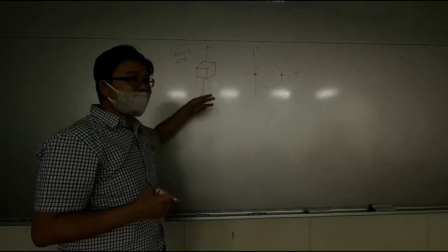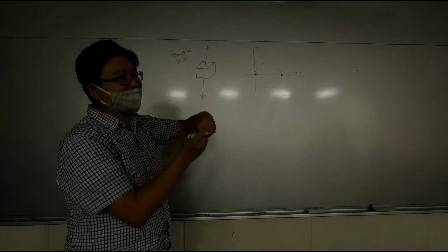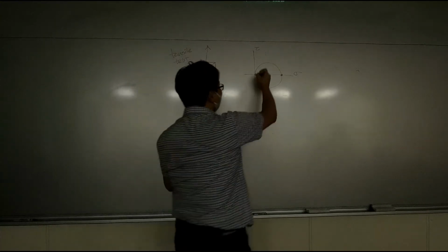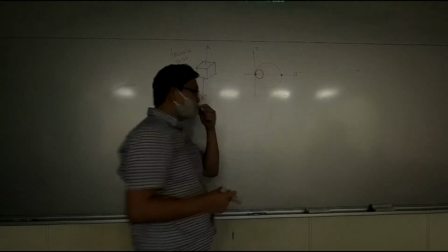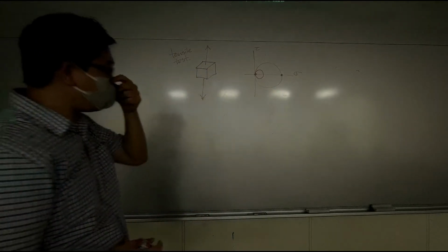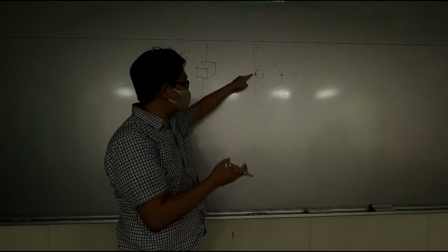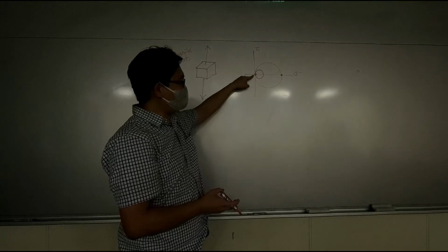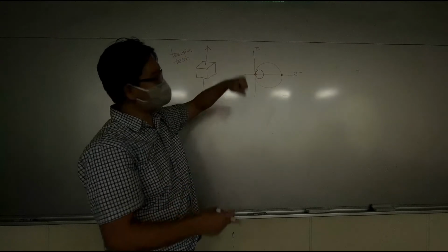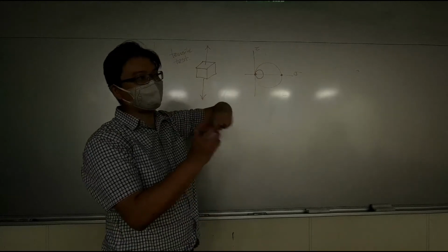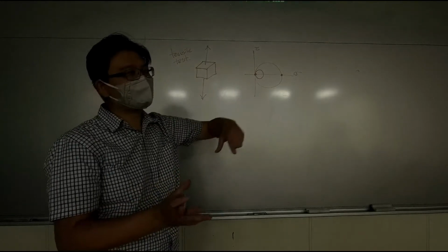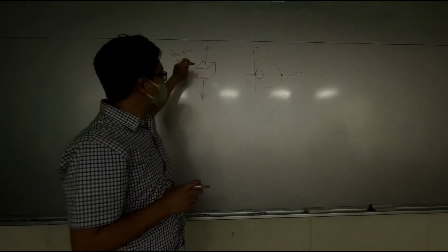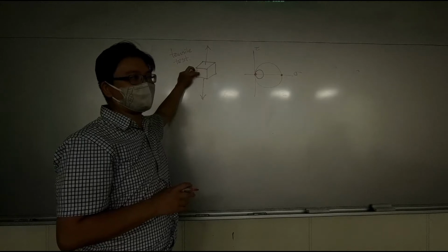And at the beginning of the tensile test, when you are not applying any force, or when you are applying a very small force, the Mohr circle of this material is having a smaller size, but tangent to the origin of the coordinate. As the load increases, the size of the Mohr circle increases. When the circle reaches a point, then this material starts to yield.